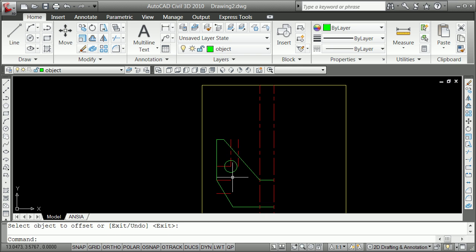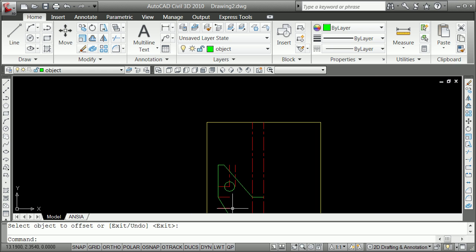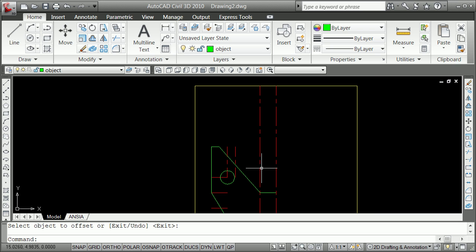and again here you'll see that if you do a fillet on this one and then a fillet on another, there are all kinds of different ways to do this. So I'm going to introduce you now to the extend command, which is the opposite of the trim command. Once again, fillet radius 0 is assumed since you haven't changed it, goes there, and then the command is extend. Extend is the opposite of trim. It's EX. Extend that there.